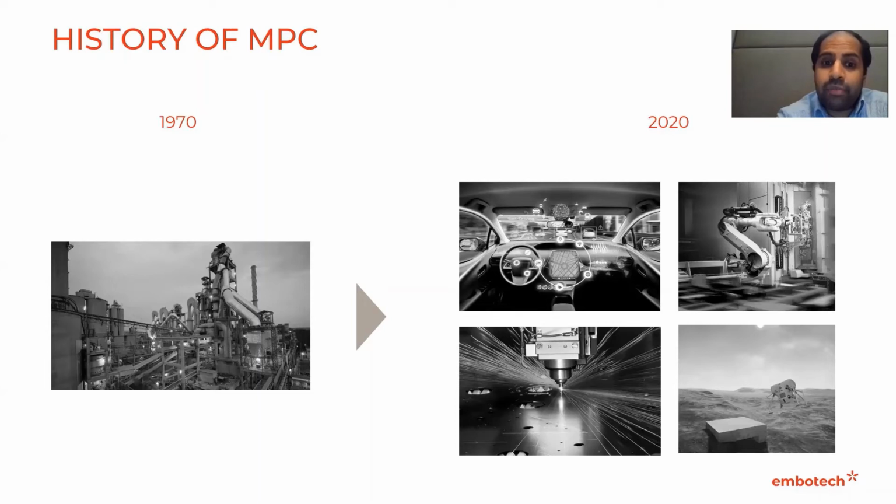One other big distinction from the early developments of MPC is that in the process industry, you still have an operator sitting there, and you know exactly what is happening. What I mean is that you have a set point which you need to follow, but you know exactly what the set point curve looks like. If you take autonomous driving, you don't know in advance what the driver will be doing, so you need to be capable of handling any upcoming reference change.